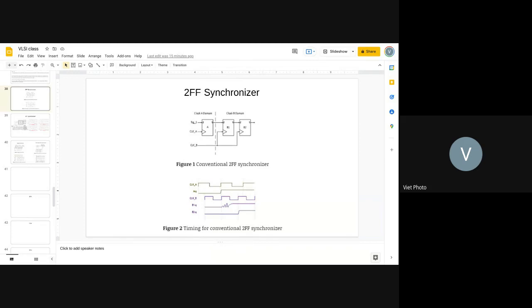That's why I said that the metastability happens at the second position. Yeah, but the third one, that's what it gets to, when it happens from that time to infinite. No, it's not finite. When it happens, it can get back to the correct value. It's just that when we said the metastability happens and then it is taken to infinite, that's only a scope of certain cases.